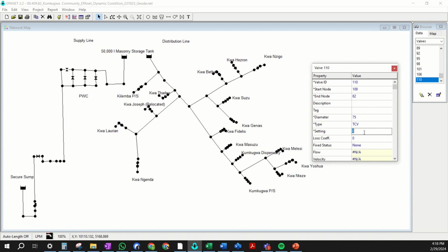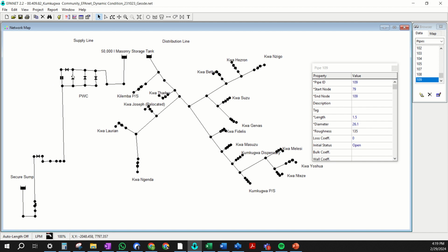So a higher number will make more water go to the chlorinators, and a lower number will open the valve and make more water go to the bypass. And we want to get about 50 to 60% of the water going through the bypass. So I'll start with a valve value of 100, but then after I run the system, I'll recheck it.